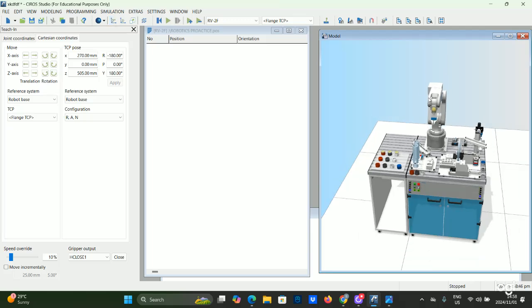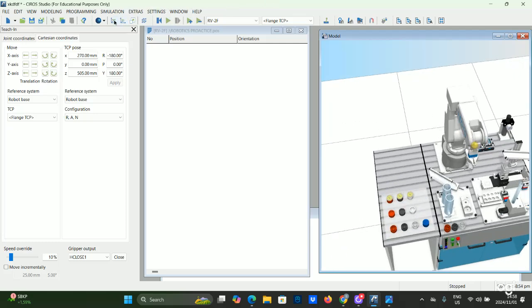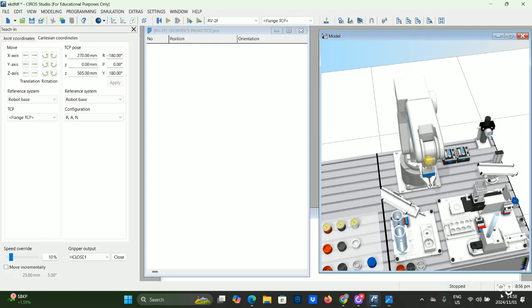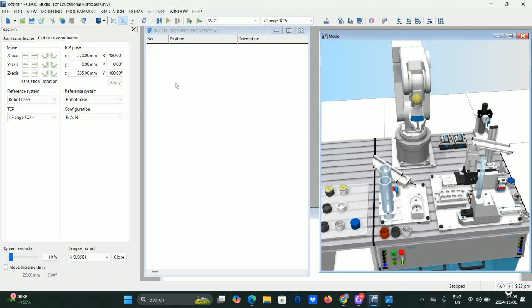So first, when you program your robot, you need to have a position that's called home, right? So the home position is sort of like, let's say your robot is assembling a workpiece. After it finishes assembling the workpiece, it's going to maybe drop the workpiece on the second chute, and after it's done, it needs to return to a position where it can await the arrival of the next part, right? So that's your home position. Now, let's say I'm trying to define my home position here, right?